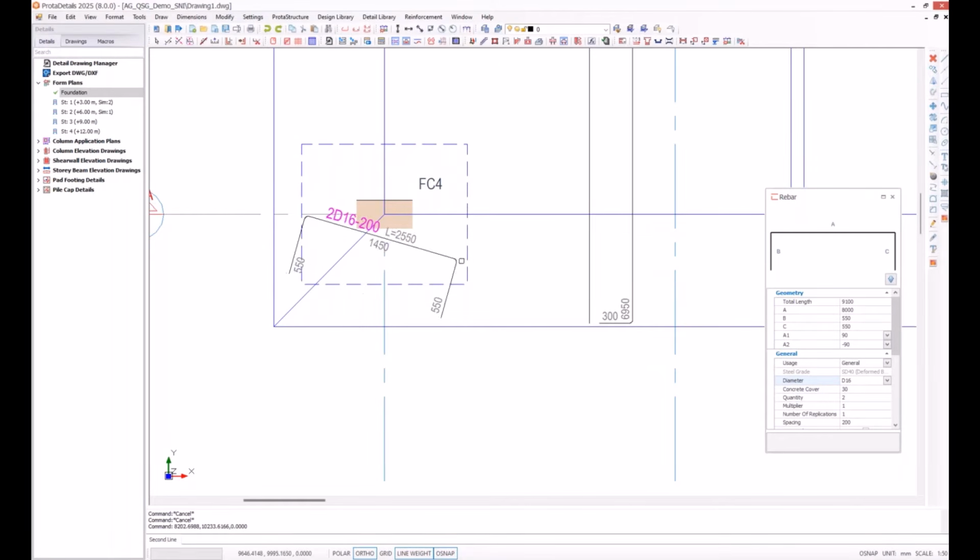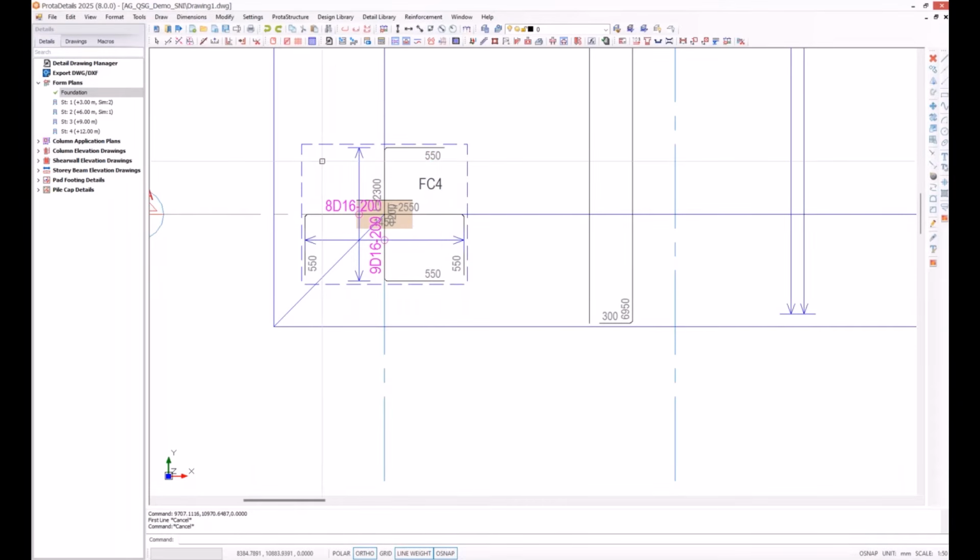It's going to be between these lines, and it will span from here to right here. You see that as I was showing the span, it calculated the number of rebars automatically, and I will do the same for the other direction bar. Yes, it will span from left to right. Okay, so this is great.